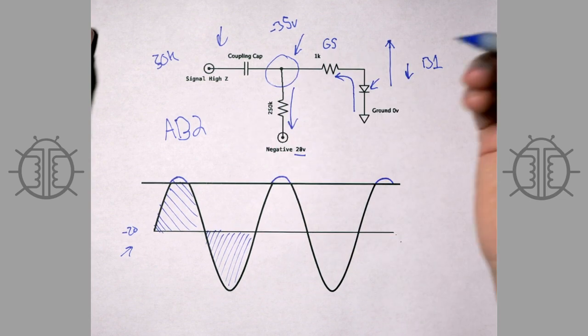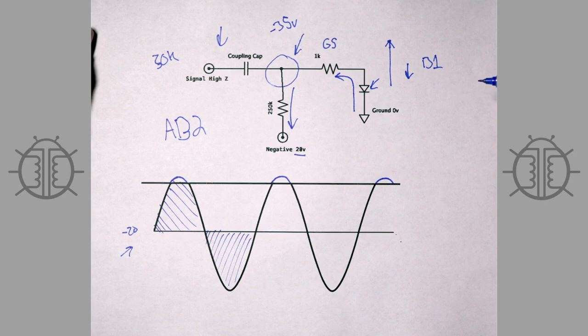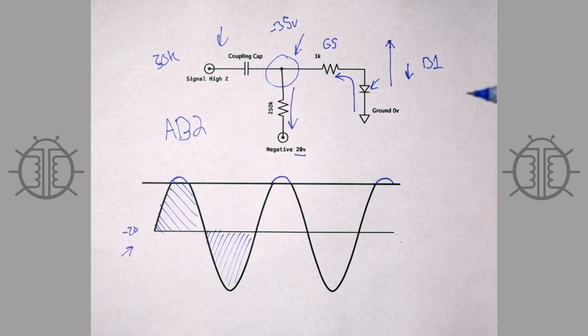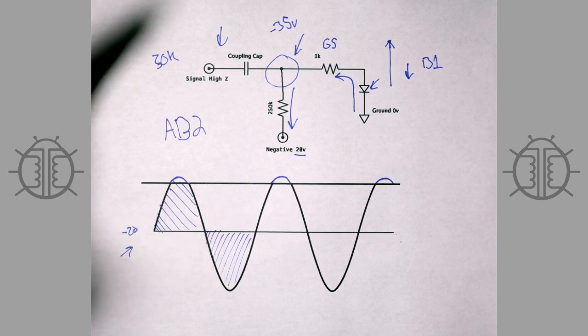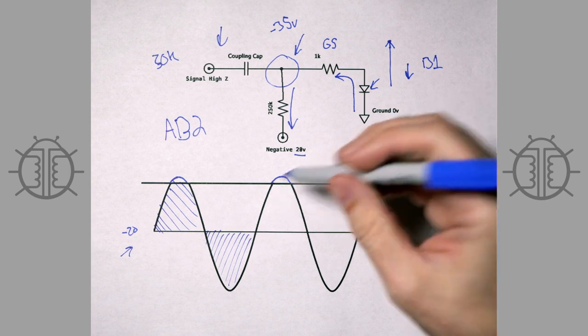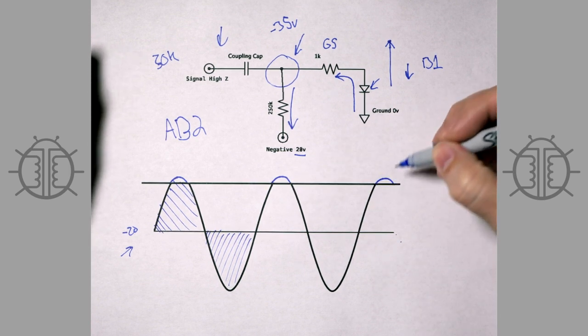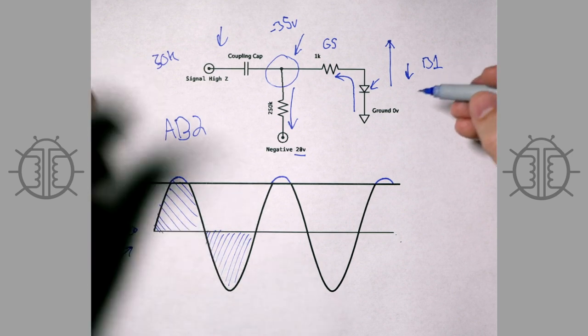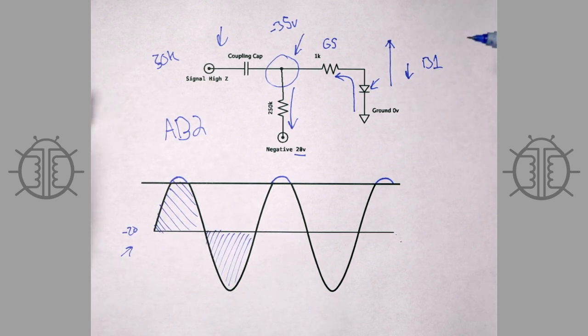You're going to need to add something called a follower stage, and that usually is a MOSFET or a high voltage transistor or a cathode follower tube stage. So you're talking about an entirely new stage over here, adding more complexity to the circuit, which is fine. You're going to get more power out of it too, because as you drive 0 volts, the grid actually starts acting kind of like a screen and accelerates the electrons towards the plate even more. And that's great. You can do that.